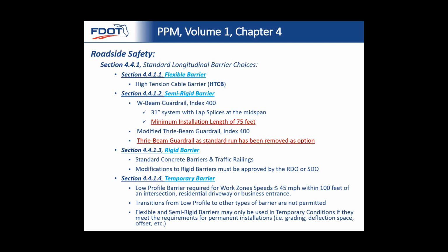splices were located on a post. That created a higher shear location through the bolting location, so putting the mid-span splice at that location puts that bolted connection in pure tension instead of in shear, and it allows it to contain and redirect a larger vehicle.